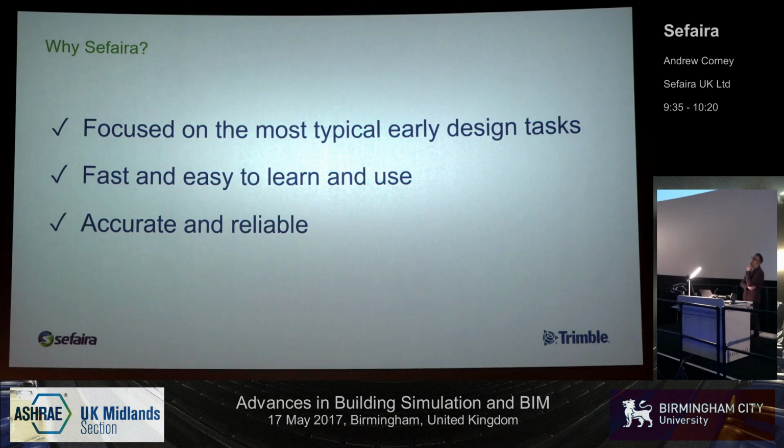Okay, great question. So I think the question, in summary, is how is Sefaira doing the efficacy of the natural ventilation calculations in EnergyPlus. Yes, we are using the airflow network calculations, and it takes a little bit longer because of that. So that's one of the reasons why I didn't want to show it today. What we are limited to at the moment in our interface is not to have interzone airflow. So the zones are all single zone studies.